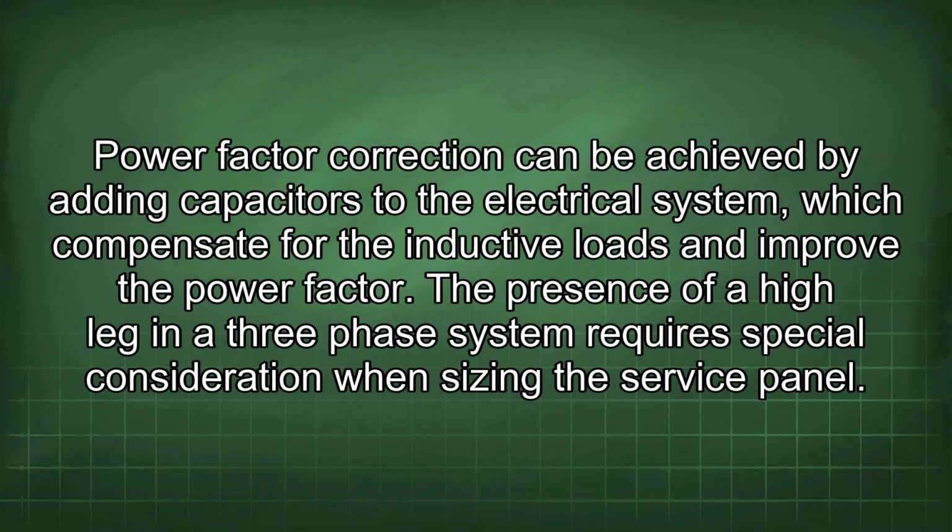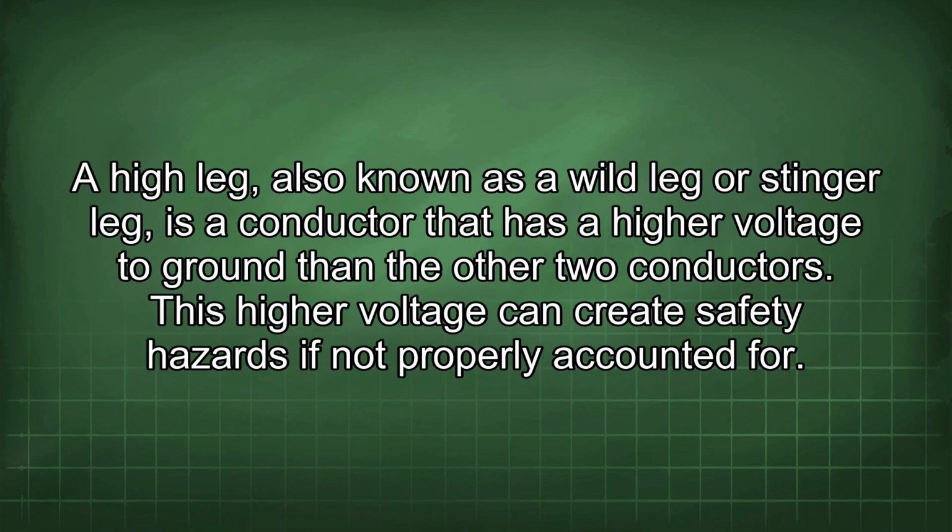improve the power factor. The presence of a high leg in a three-phase system requires special consideration when sizing the service panel. A high leg, also known as a wild leg or stinger leg, is a conductor that has a higher voltage to ground than the other two conductors. This higher voltage can create safety hazards if not properly accounted for.